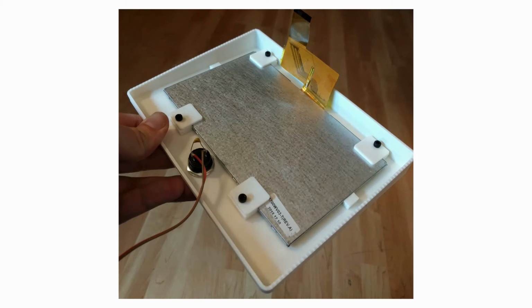Is it evenly spaced or is it more green bits? No, it's 888. It's actually not common with video, right? Yeah, this is pretty high. This is a lot of color resolution. Sometimes it can be like 16, and then they'll do like 565 or something. But this was 24. We ended up using, of the pins on the device, like 30 of them just to get the video to the LCD. That's right. But timing it was nice because I already had a VGA output from the previous dev board, so I could just adapt it pretty easily to this.